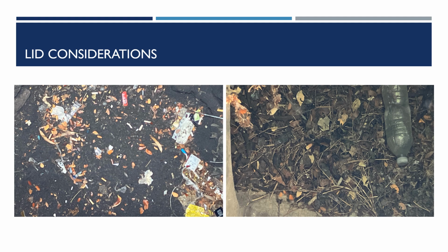LID PBMPs are susceptible to clogging from sediment, leaves, and debris that could lead to premature failure. Suitable pretreatment systems such as sedimentation basins, forebays, or manufactured treatment devices such as hydrodynamic separators help maintain the infiltration rate of the device without frequent and intensive maintenance. If LID PBMPs are not feasible, an LID waiver will be granted, but projects may still be required to implement